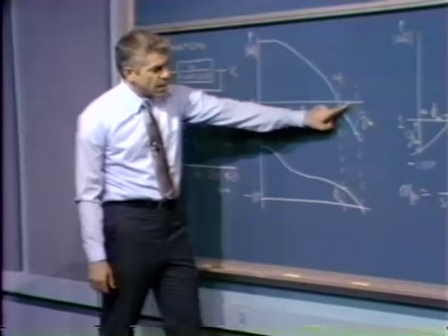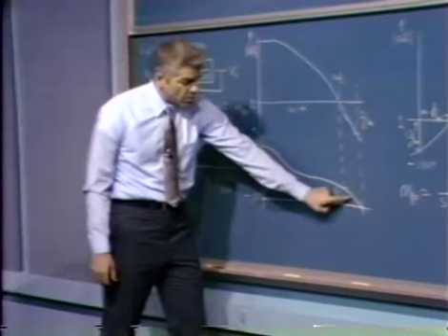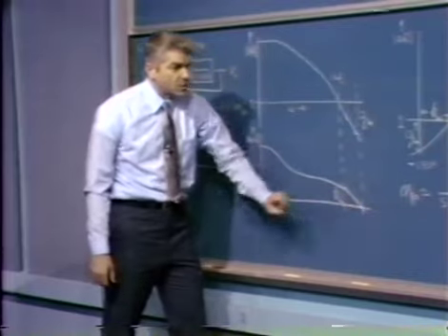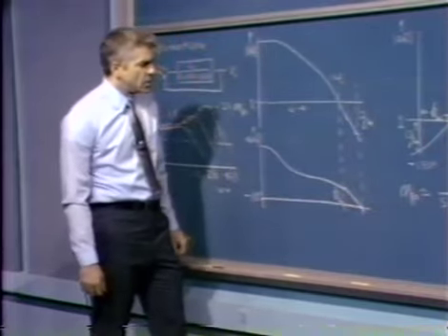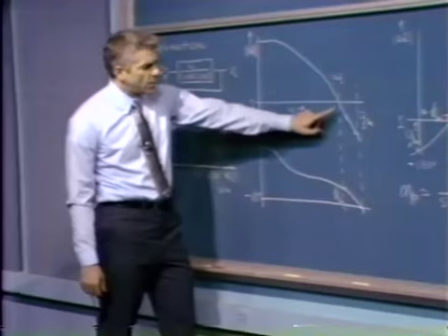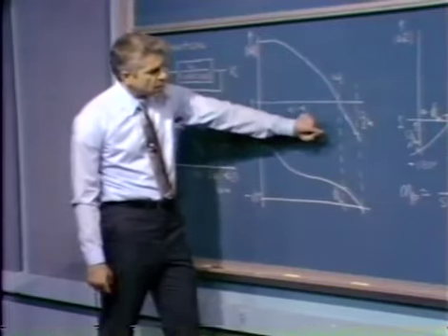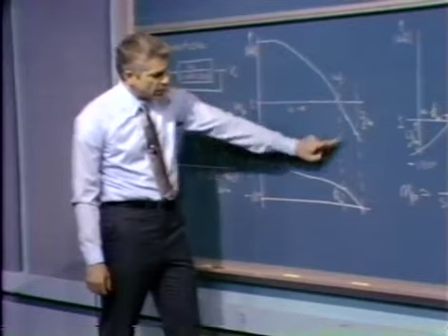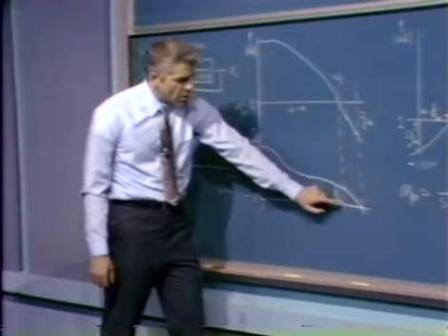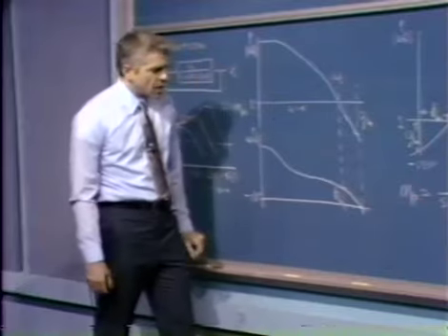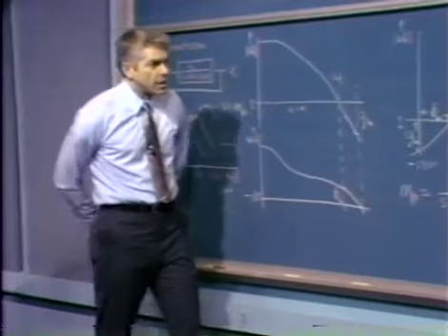Because we've increased the AF product, we get greater desensitivity, but unfortunately the price we pay is one of reduced phase margin, consequently reduced stability. So there's almost always that trade-off where higher values of crossover frequency and greater amounts of desensitivity invariably lead to smaller phase margins, consequently less relative stability.